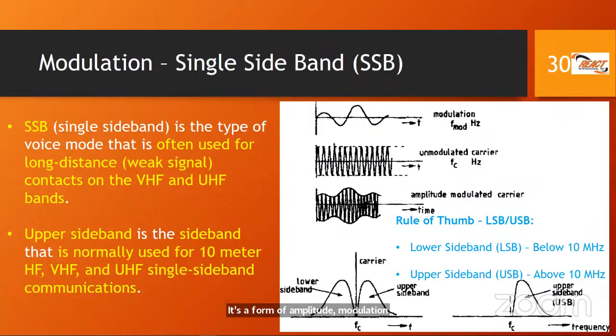All right. So there are a couple other things that we need to know about single sideband, and these are some of the advantages as well, right? It's advantageous. So again, we repeat this diagram here for you so you can see the AM signal, represented sideways here, and we strip off the carrier and the lower sideband and we're just left with the upper sideband, for example, right? Or what we call single sideband. Single sideband could be either upper sideband or lower sideband.